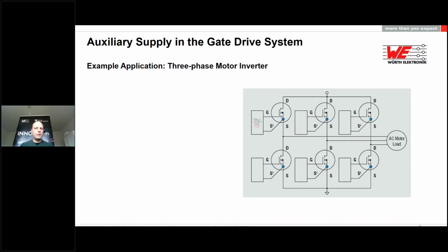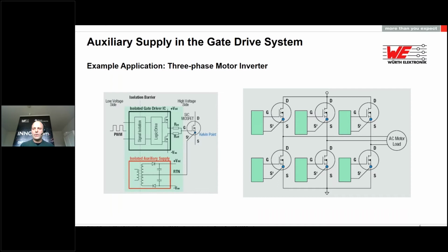Therefore, a circuit called a power inverter will provide the conversion from DC to AC using a system of switching devices in a full bridge configuration. Each switch is controlled by a gate drive IC, and each gate drive IC needs its own isolated power supply. And here comes into play our power transformer, which offers the needed power and isolation.